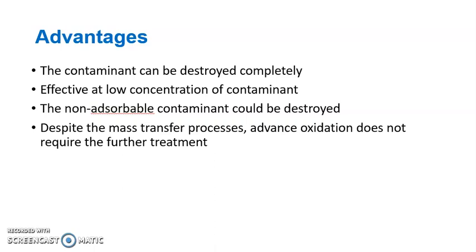Advanced oxidation processes are feasible for large-scale treatment to destroy organic compounds because they are generating hydroxyl radicals. I mentioned hydroxyl radicals are very reactive. These processes are working at ambient temperature and atmospheric pressure, so no specific condition is required for applying these processes. And very rapidly, hydroxyl radicals oxidize the organic material and destroy it, and it's not selective.